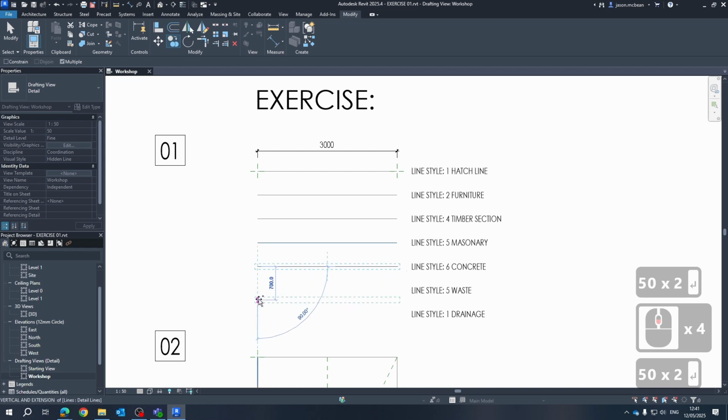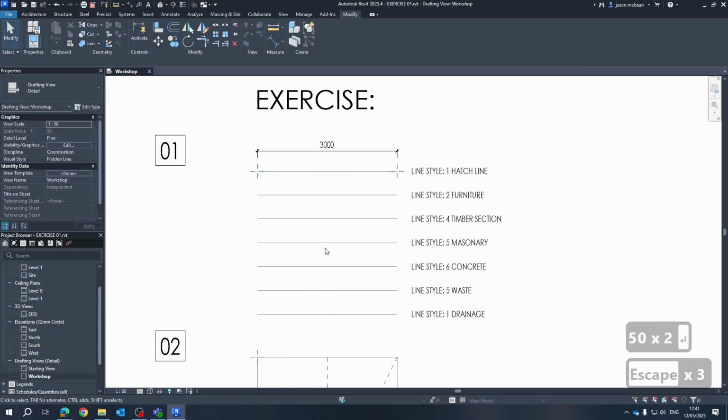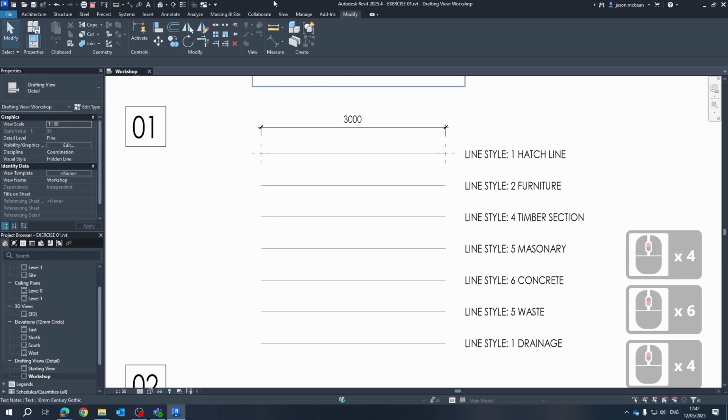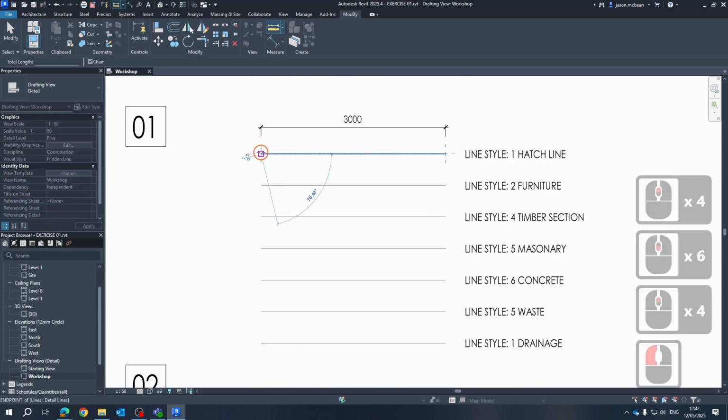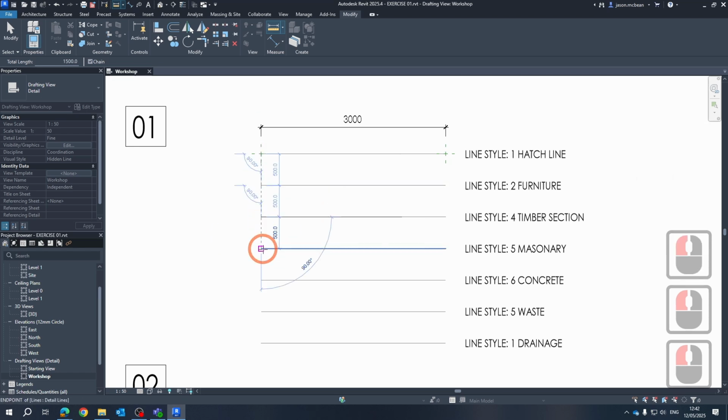So this is why drafting in Revit or starting to draft your construction drawings is going to take a lot quicker to put a drawing together, because a lot of these things you can just multiply on the fly and everything's pre-set up to work. Just note, if you don't have a good template, this is going to take a long time to get to work correctly. Okay, so I'm just going to use a measure tool quickly. You can double check and make sure that everything is 500 and you can see that it is.